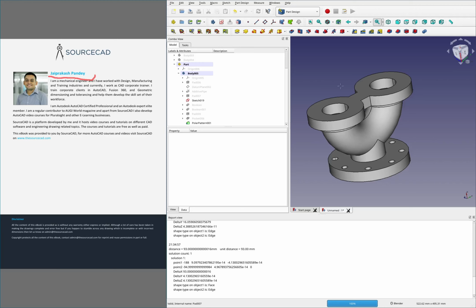I think in particular this last model probably was the most learning. If you ever have any issues with FreeCAD's modeling engine dealing with these kind of funky shapes, the Boolean stuff tends to work very well. So you convert it over to Boolean, model the two things separately, Boolean add, Boolean subtract seems to work pretty well.